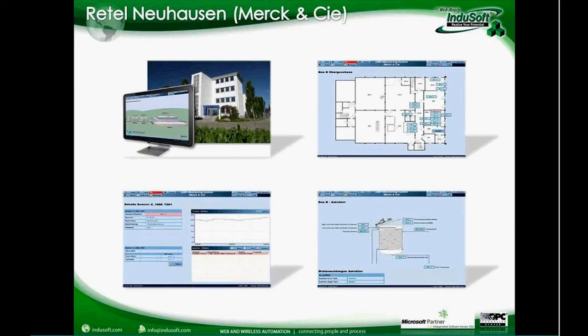pharmaceutical companies, where they also monitor the temperature and different variables of the building on the fly. And they designed a very nice template with InduSoft, and every new project they developed, they pretty much customize the template according to the needs from the customers. And they use the alarm management system, the event logger from InduSoft, the interface to databases, the trend control, and all the tools required to create applications compliant with the FDA 21 CFR Part 11 required for food and beverage and also pharmaceutical industries.